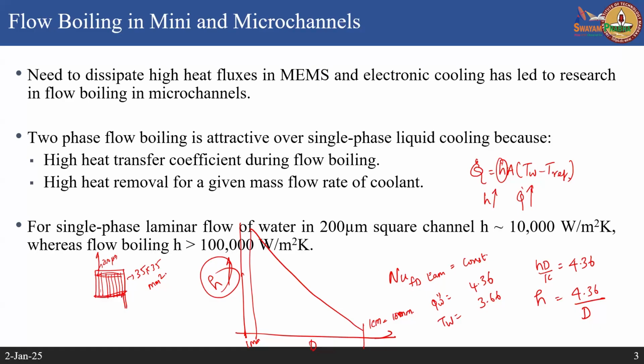Now, on top of that, if I do flow boiling inside these micro channels, I also increase the heat transfer coefficient by at least another one or two orders of magnitude. So, that is the idea why flow boiling in small size channels is quite important.